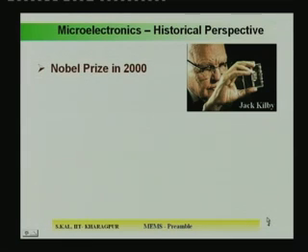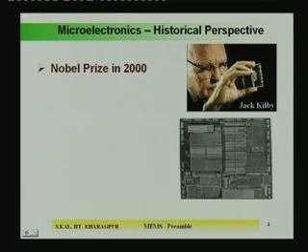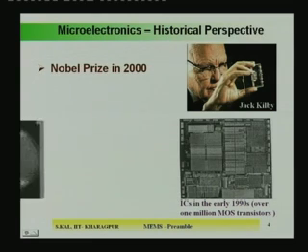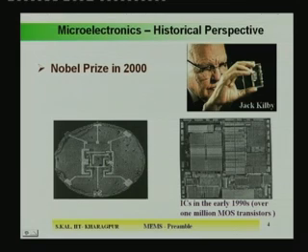So, from that time onwards, people have not looked back and are proceeding forward, particularly in the context of miniaturization of different components and making integrated circuits. Now, in this picture you can see a chip containing over 1 million MOS transistors, and that is from the early 1990s. If you compare the revolution in the integration of components, you have to go back to the first integrated circuit, which was also monolithic, and that was made in the 1960s. 4 BJTs and several resistors are connected together with some metal line. You can see there a metal contact, a metal bond pad, and here is another metal bond pad, and the 4 transistors and several resistances were integrated to get a circuit function.